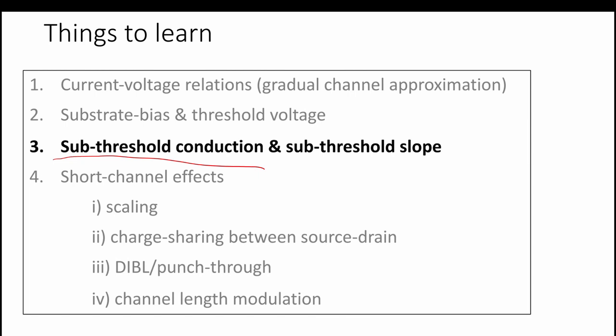By the gate voltage, we can control the current flow, and with the current flow we can control the intensity of the light. Whenever we want to turn off the light, we give zero gate voltage and turn off the transistor.